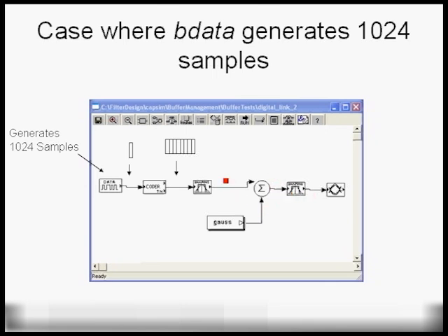We're stranded with 7 times 128 samples. Then what happens is the kernel visits the data block, the binary data generator, again, and it'll generate another 128 samples. And it gets upsampled by a factor of 8. The Gauss block generates another 128 samples.